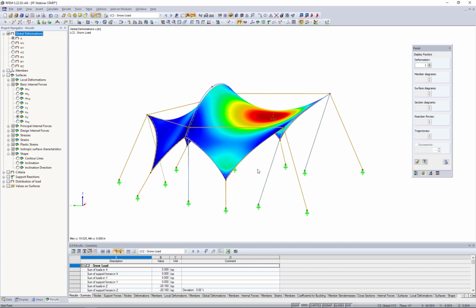But when we're getting into these fabric membrane structures, and in particular these very unique geometries, it's incredibly difficult to determine what these minimum wind loads should be from the standards. So the hope is to use a program such as RWIND Simulation for a CFD analysis to better understand what these wind loads should be set to and how we can incorporate the new loads with our structure design.